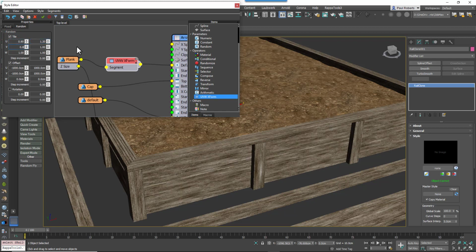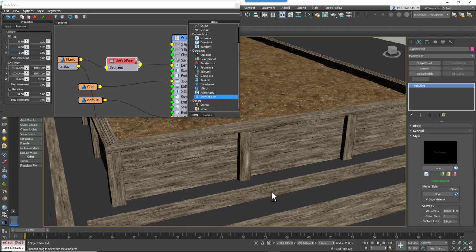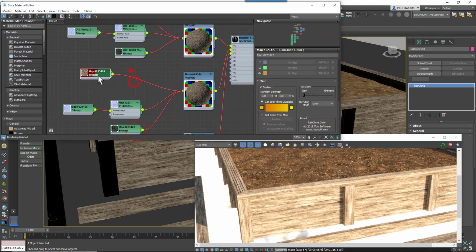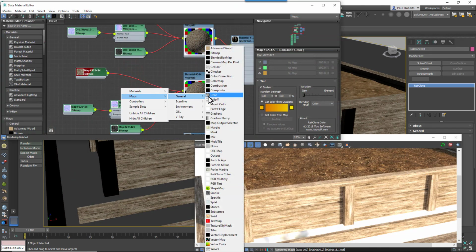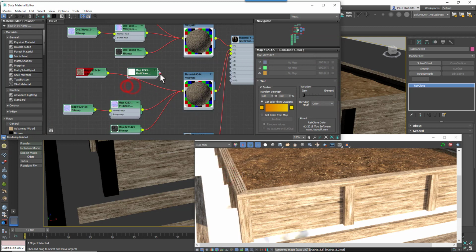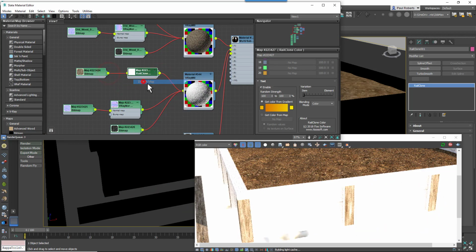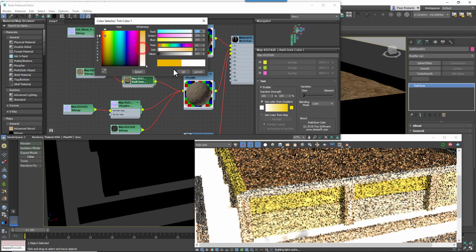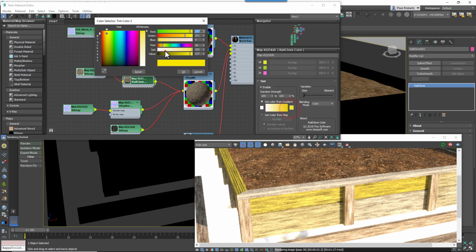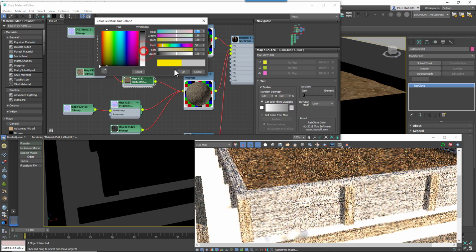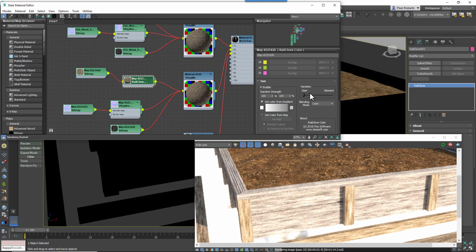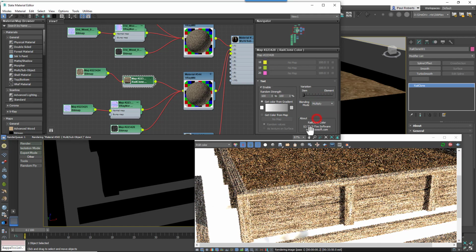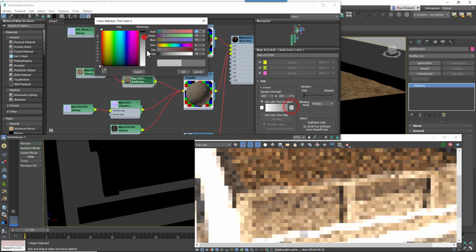Now let's randomize the textures. So open the material editor, add a RailClone color material to the wood's diffuse maps. Enable tint. Change the gradient settings so that it's white on one end and grey at the other. And then finally, change the mode to multiply. Then each time the segment is used, its brightness will be slightly randomized.